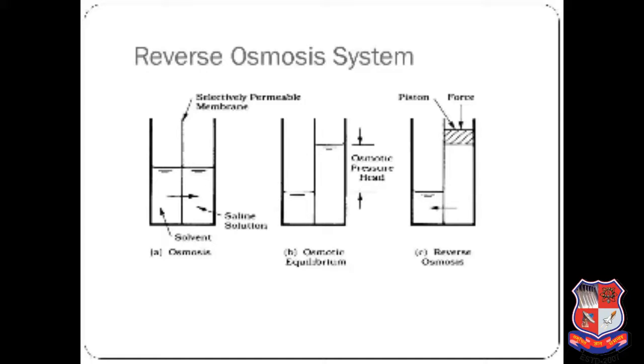Two materials make up the bulk of commercial RO membranes: cellulose acetate and aromatic polymer polyamide. Reverse osmosis membranes do not have definable pores in the way that the films used in ultrafiltration do. There are only spaces between the fibers making up the film, which can take up water because of the acetyl or similar groupings which form the surface. The dense layer of active surface is about 0.25 micron thick, supported by a thicker porous layer.